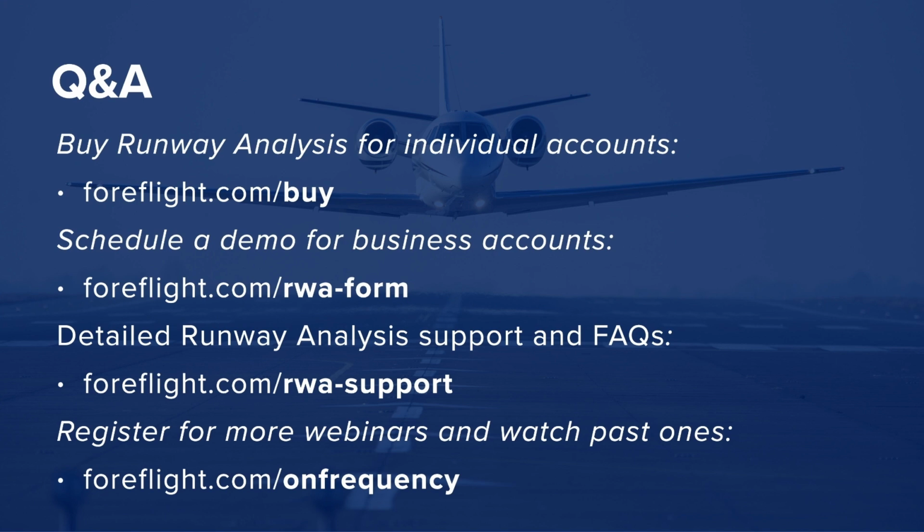So if you want to do a what if scenario for, let's say Aspen, and you want to see what it's like at 18 degrees, you simply enter 18 degrees on the takeoff page, and right away we calculate a new maximum takeoff weight with what the limitation is.